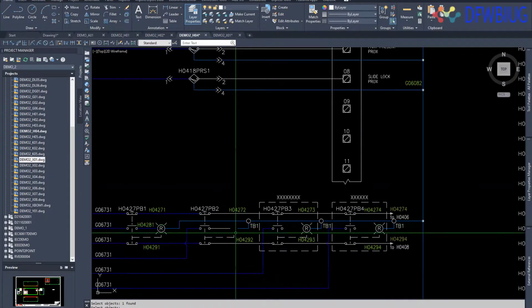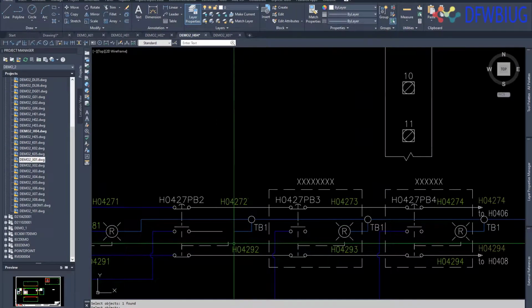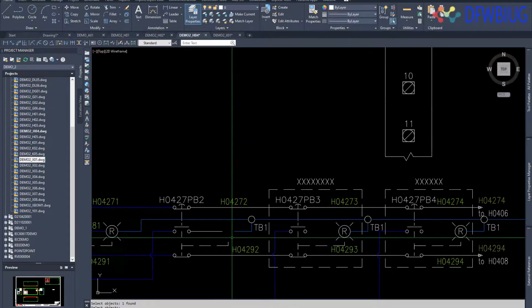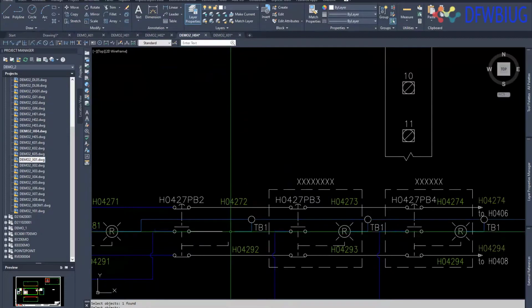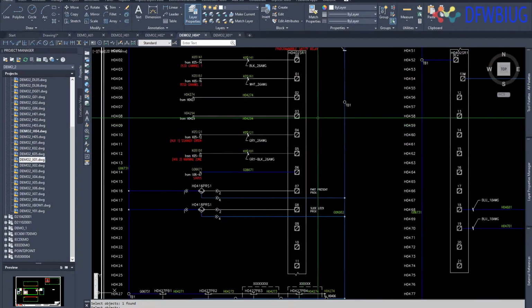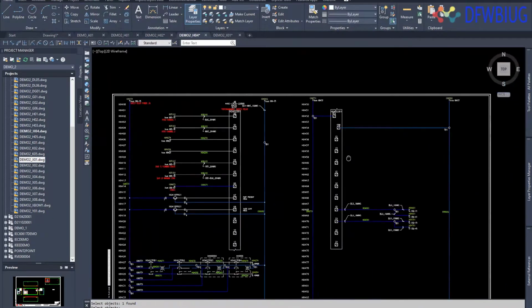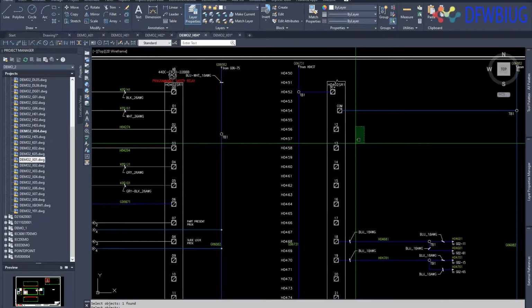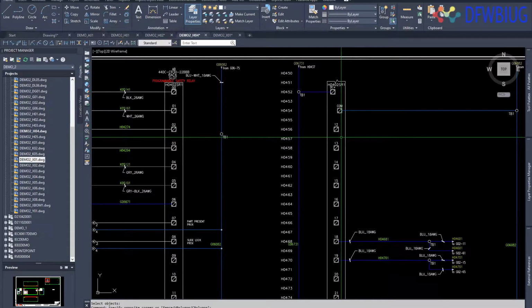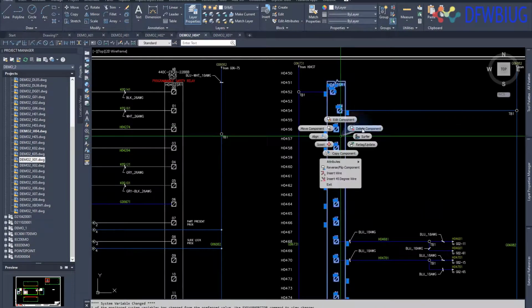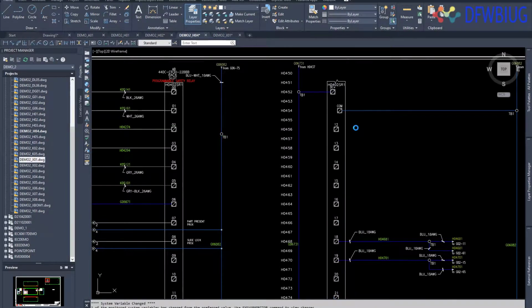Okay, what did I just do? Well, right now, that light is still in the database, and its values are still in the database, and its connections. That's something that will corrupt your database. When I go to do a report on this sheet, I'm going to run into issues. The only way to safely get a component from here is to delete the component.